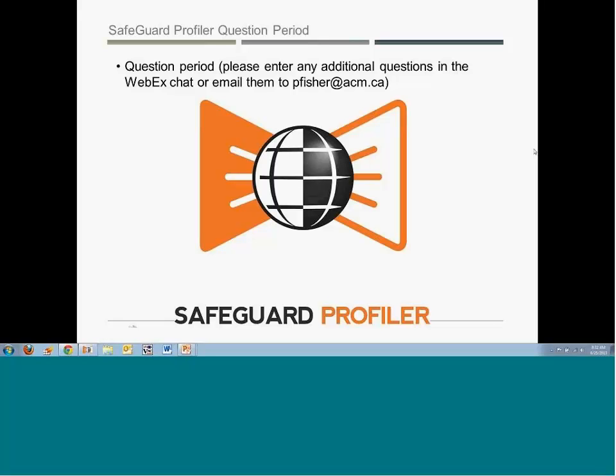Another question is, how does Profiler help reduce the number of safeguards? And that was in the bow tie. We replaced 5 alarms with a single alarm, reducing your overall number of safeguards from 7 to 3. So we reduced a pretty considerable number of safeguards through the bow tie method. And that is unique to Profiler in that it links the LOPA, the power of a spreadsheet LOPA, with the visualization of the bow tie as you're doing that.